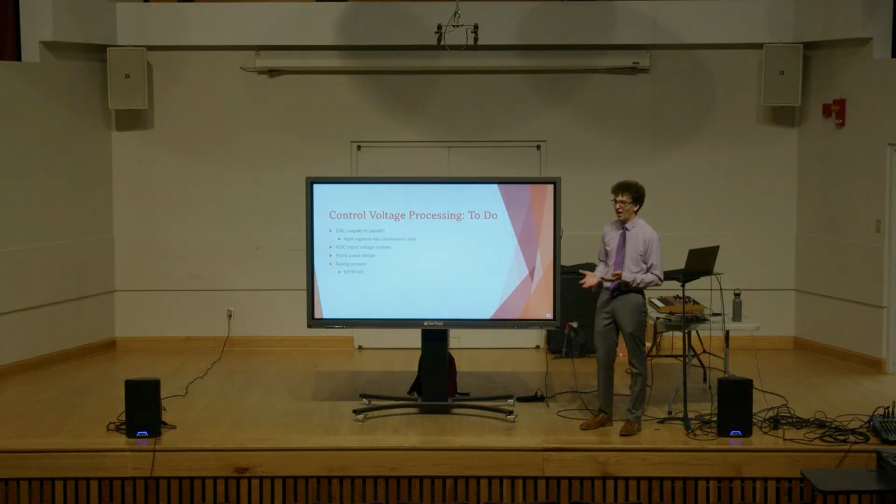Since I haven't done a whole lot of research on ADCs, it seems like the sampling time for ADCs is generally slower than DAC output settling times. So the DAC can often spit out voltages consistently faster than the ADC can sample them. So the cycle time I just showed you would probably be multiplied by 2 or 3 times, depending on how long the ADCs take to multiplex in and read all these individual control voltages, which is why running DAC outputs in parallel would be very nice.